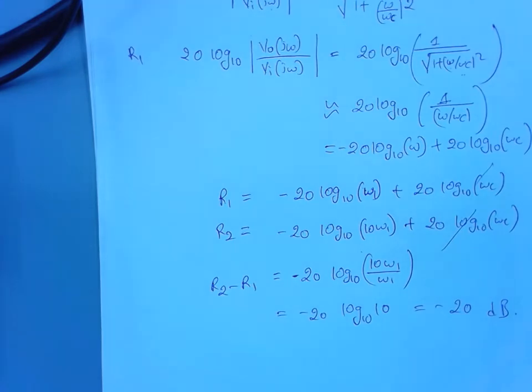That means a first order response will cut off the high frequencies very slowly. If you want a very sharp response, then you want to build higher order filters. Okay, so the higher the order, the faster the cutoff will be. But there are other complications you'll have, so there are other techniques to take care of those complications. So in practice, you'll hardly ever build a first order filter, because usually you will need a much sharper transition, right? So higher order filter design is a topic in itself. We may get to it a little bit in this course, if we go fast enough, but maybe not. But anyway, that's where we will stop.